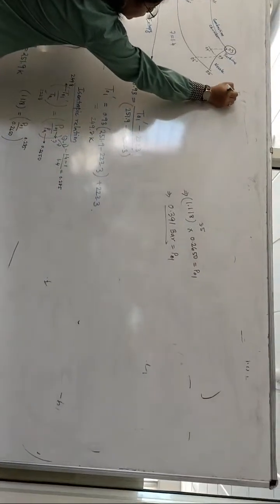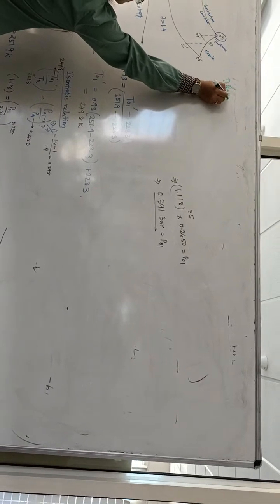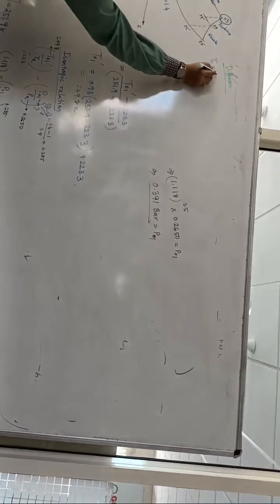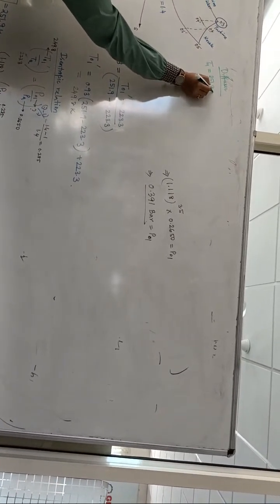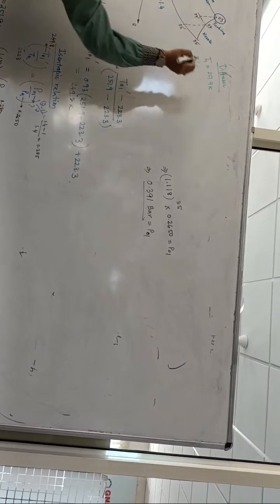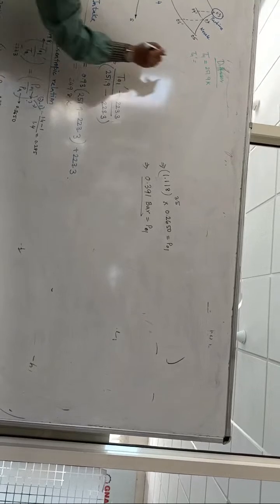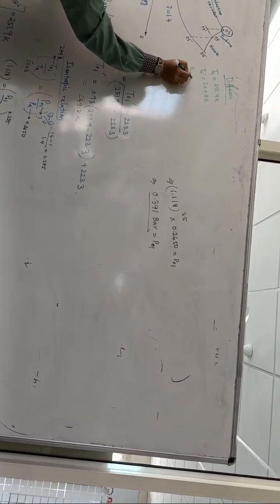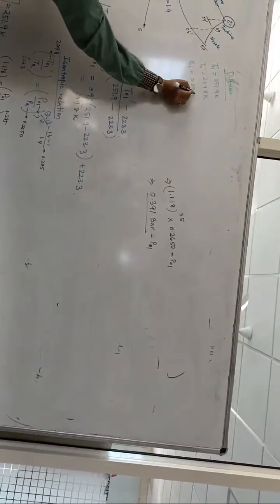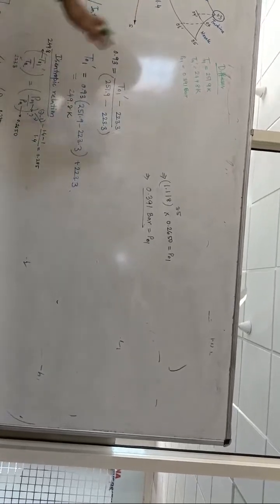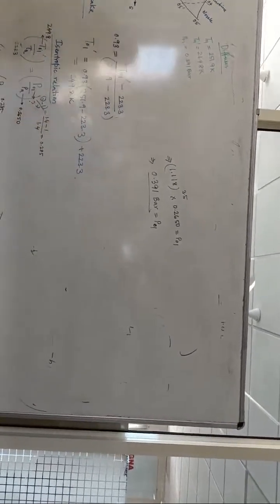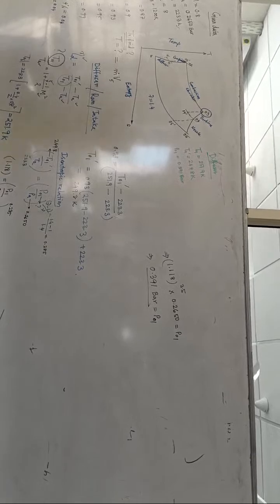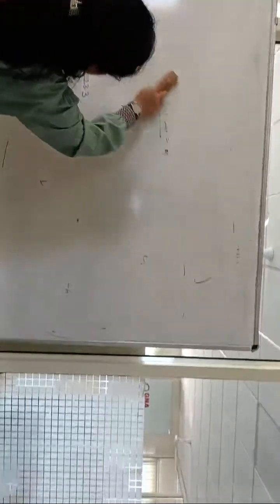So here write separately diffuser and write the temperatures. T01, what's the value? All the values, write it here. T01 prime, what is the value of T01 prime? 249.8 Kelvin. P01 is 0.391 bar. Now whatever we have calculated, I have written in one point. Because PA is given, TA is given, so I am not writing those parts. So the diffuser part is done, so I am rubbing this diffuser thing.